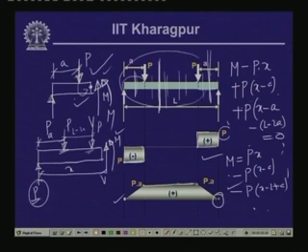So, and also if we substitute x as L minus a, we get the value of bending moment as equal to P times a, which is at this point. So, as you can see now from the free bodies of the different segments, we get a bending moment which is varying like this. Now, if you remember, we had looked into that wherever the shear force is equal to 0, the bending moment is expected to be constant, because dM/dx is equal to minus V.